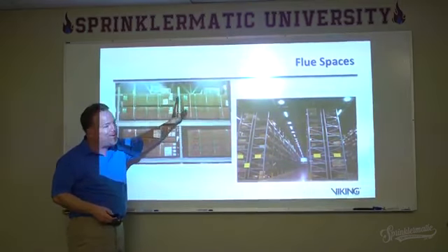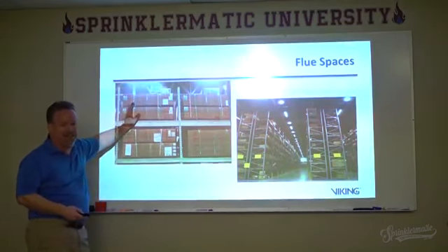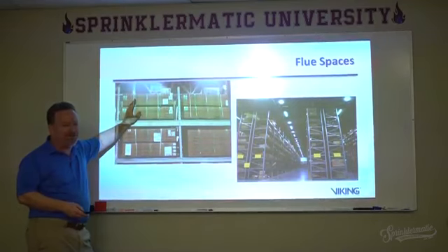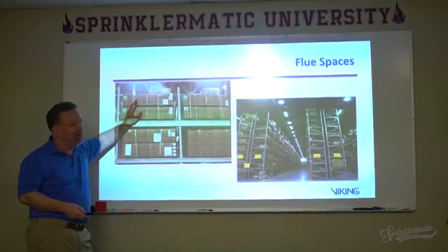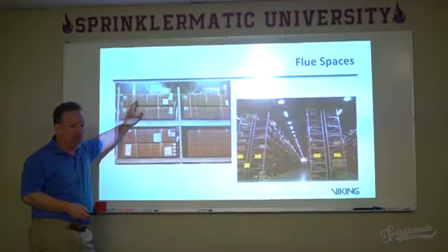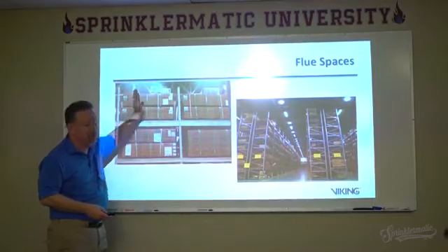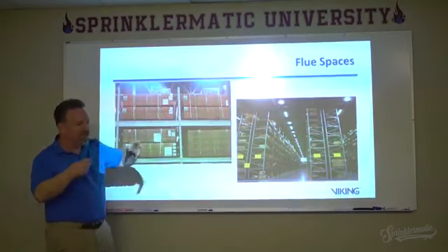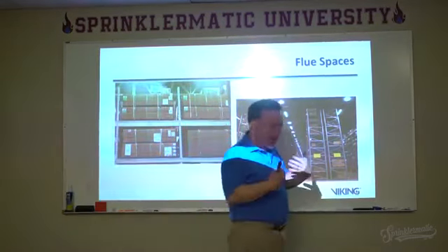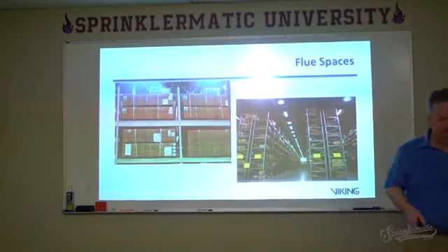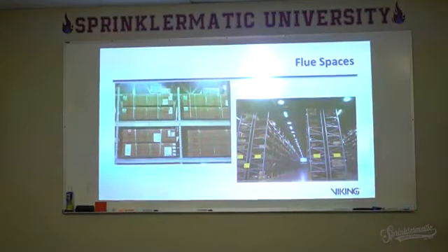But if I push it all the way over, I can get a third box in there. What does that mean for me? More storage stuff. Okay, I can store more stuff. Better money, more money. What has it done though? It's choked off the ability of my sprinkler system to operate. So we need to maintain our flue spaces. Critical. Once again, it's that balancing act between what I want to do as an owner and what the system is going to be capable of doing.